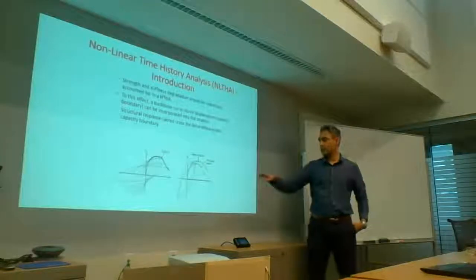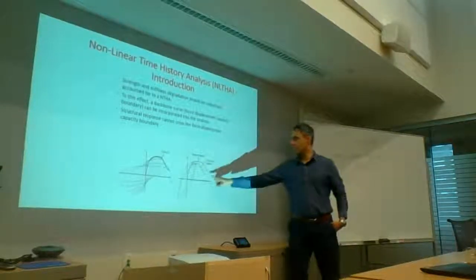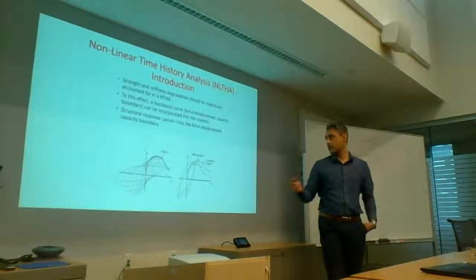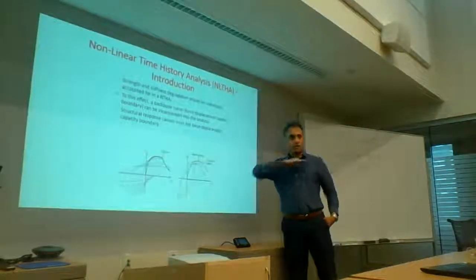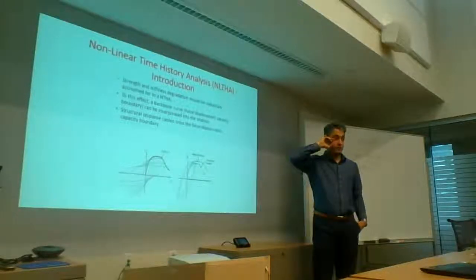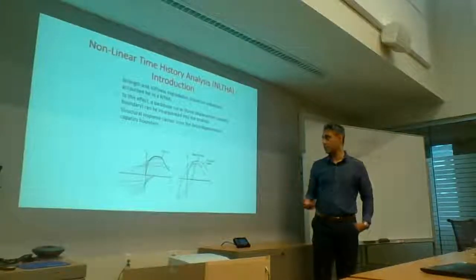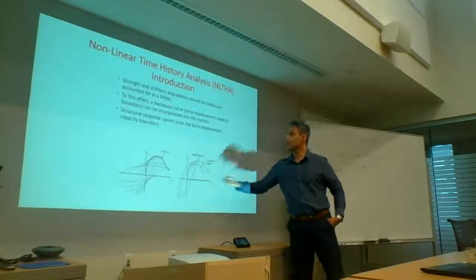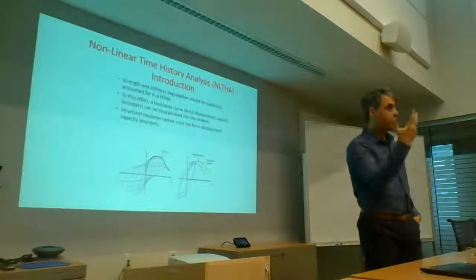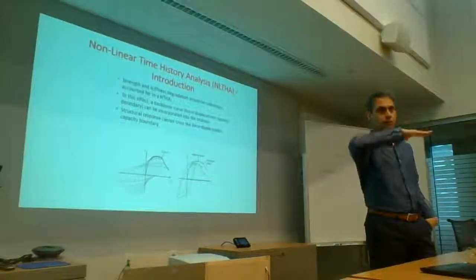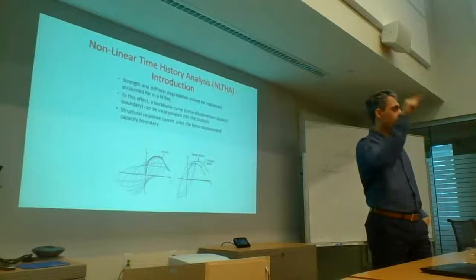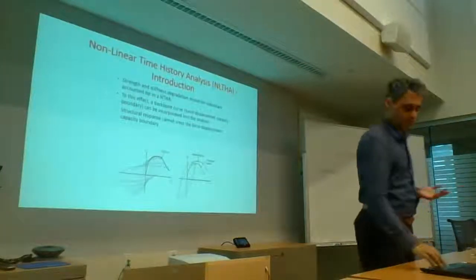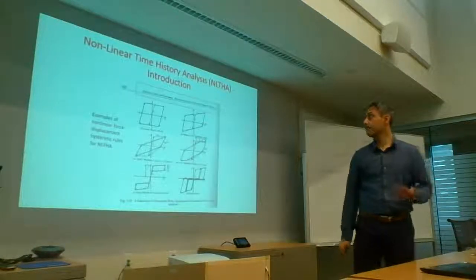The thing is that your force can never exceed your boundary, because it's just physically impossible. So as soon as it hits that point, the force gets capped, and it turns into a nonlinear problem, but you have to tell your program to use that. And I think that's what we're doing. Even when we were looking at the pushover with some degraded capacity, the program will never give you more than what that level corresponds to. So it's important to think of that.